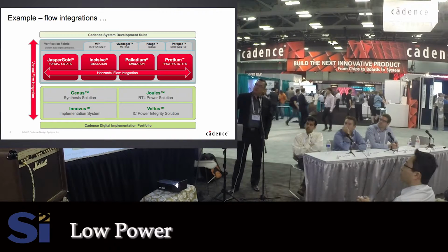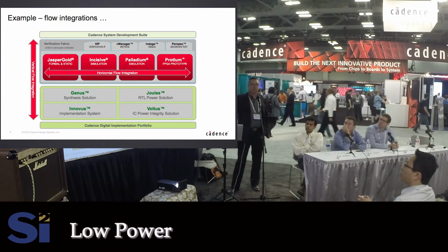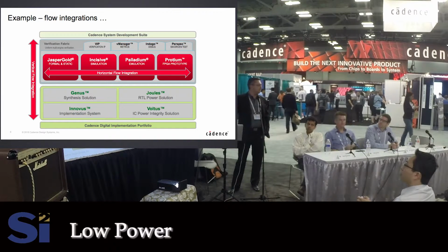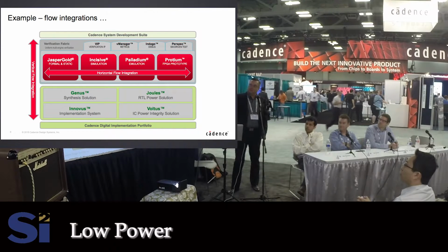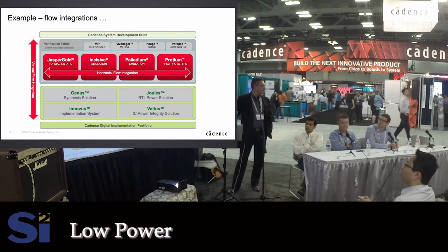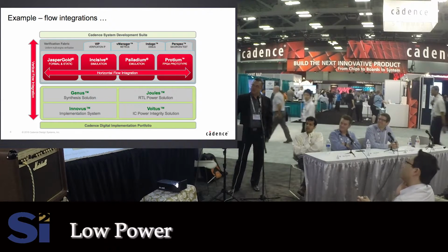You then abstract it into the higher level flows, even up to virtual platforms, where you have essentially TLM-based, transaction level based simulation. Where we are certainly not doing great stuff yet is at the system level, where you have transaction level based simulation, being able to consider all the changes, right? So with RTL power estimation, I think you gave us like a B- or C, somewhere there.